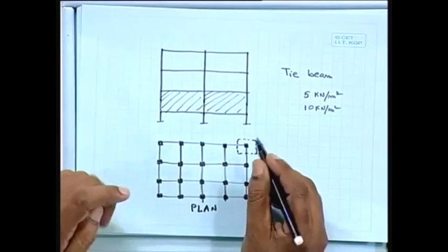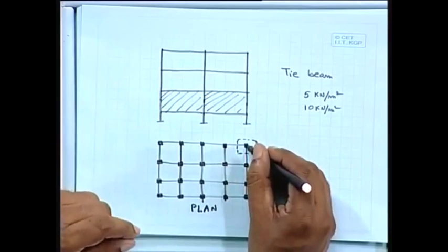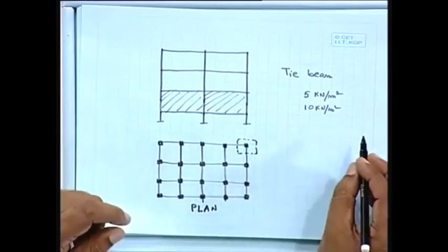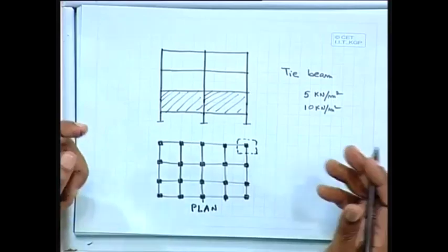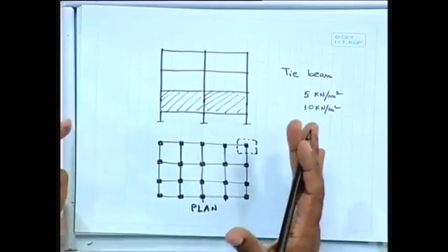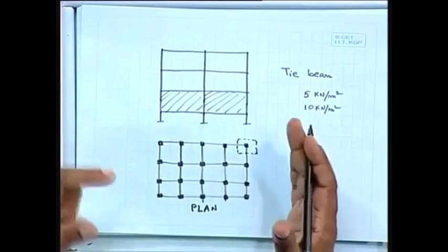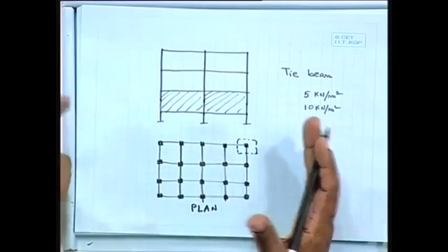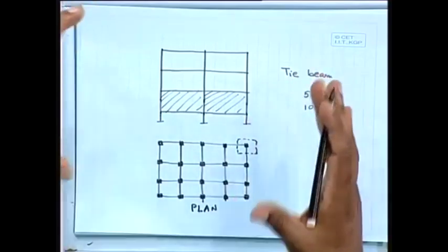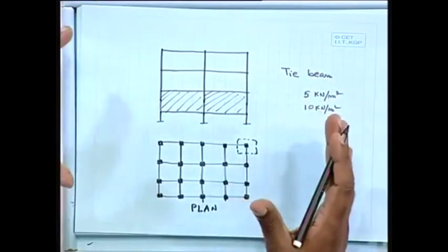of the footing, because if we just simply say 300 millimeter by 300 millimeter, or 400 millimeter by 400 millimeter for that column, compared to the dimension of the building, you can almost consider that the column dimension is just like a needle. That means if you just keep it over the soil, it will simply pierce.